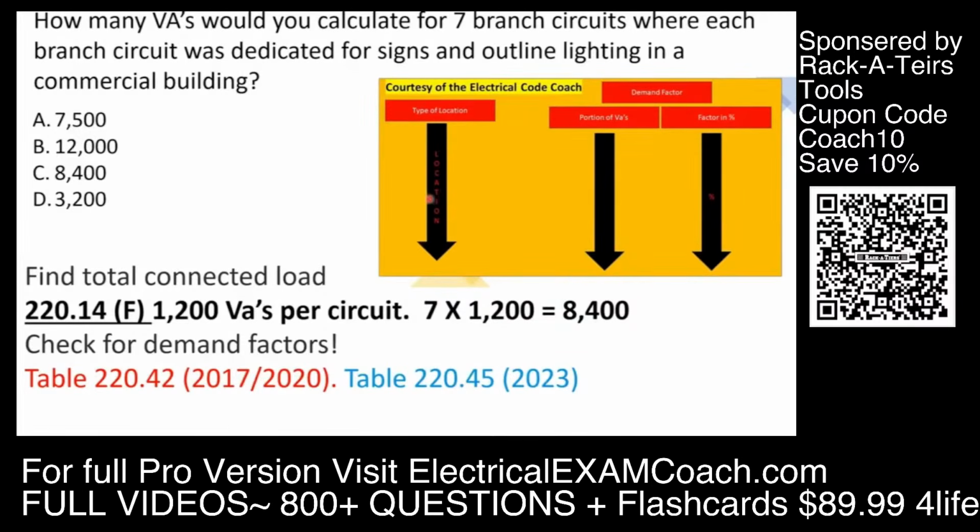When we get there, we're going to start on the left-hand side of this table, and we're going to look for our type of occupancy. It does not mention a generic commercial building. It only mentions dwelling units, hotels and motels, so on and so forth. So if your area is not listed, you have to go down to the bottom to all locations not specified below. Then we cross over and find out that there is no demand factor when you're dealing with this type of lighting, and we're going to select C.